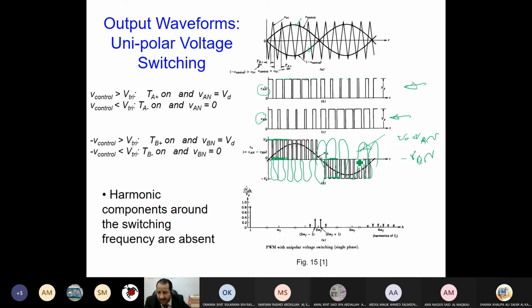So from the signal alone, you can't distinguish whether this is bipolar or unipolar. Here the modulated frequency is reduced, but the sideband is still there, as you can see here. It's reduced almost to 0, but the sideband harmonics are still there.